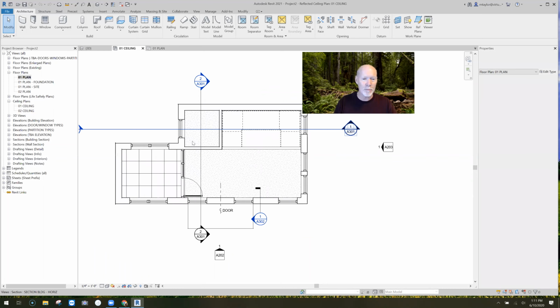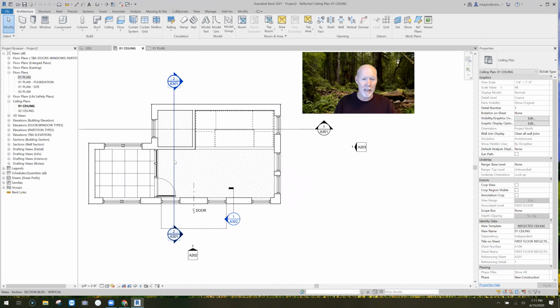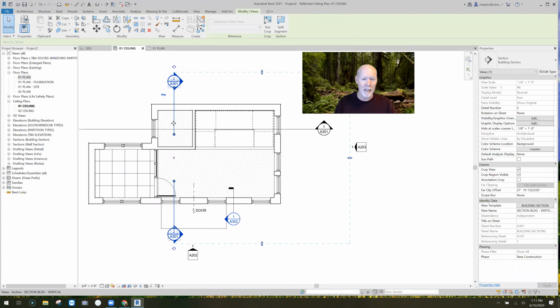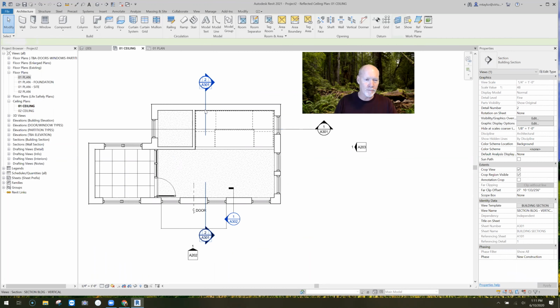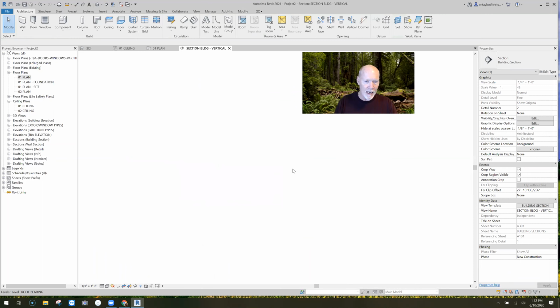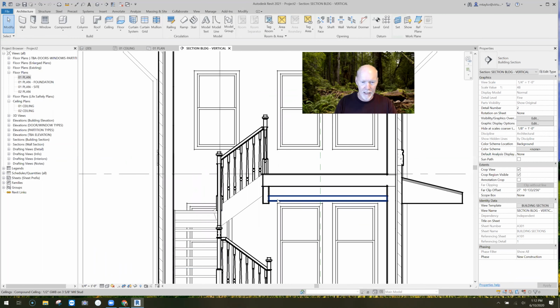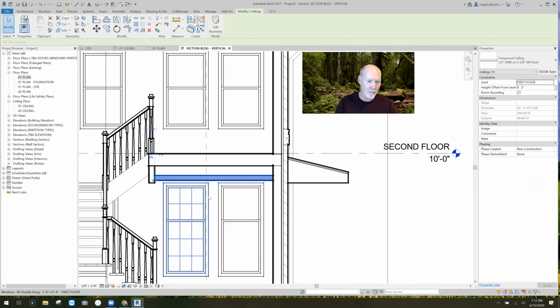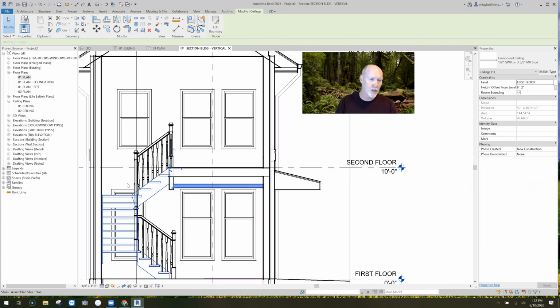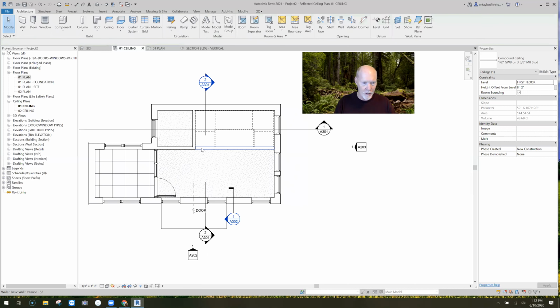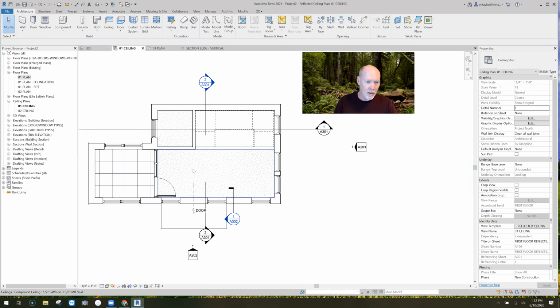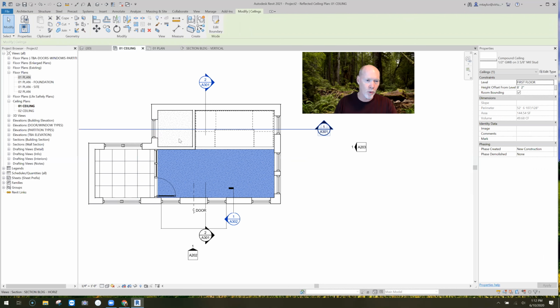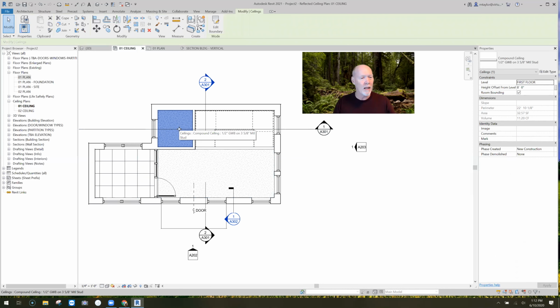So when we're in the ceiling plan, let me just show you. I'm going to move my cut over here. I dropped a soffit down, and I've got a ceiling here that's popped up over my lobby. And so when you go upstairs, of course, there's not a ceiling across there, right? So that's the ceiling there, and there's that little soffit. But this is a gypboard ceiling, and we've got a gypboard ceiling also in my bathroom. But over here in the conference room, we just have an acoustical tile ceiling.